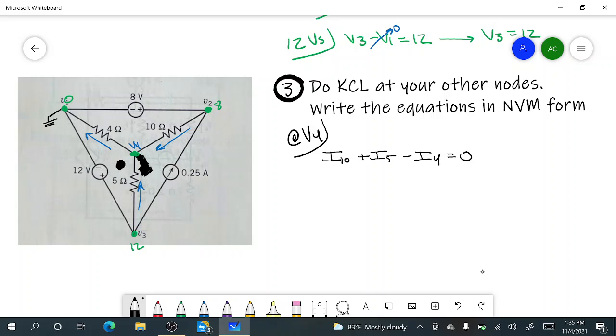All right, no problem. Now, that'd be great if you were just doing KCL, but we're doing node voltage method. Node voltage method is just a fancy way of doing, well, I should say a more complete way of doing KCL, okay? So we're going to convert our KCL equation into the node voltage rendition of it, okay? Remember this, currents always go from the plus term to the minus term. Current goes from plus to minus. So that's going to be the way we kind of think about it. I'm going to erase all of that, of course, because it's just a lot for me to have on one diagram. But if you think of it as the current goes from the plus to the minus, and remember, let's just use the 10 first. It'll start on the plus here, and then it'll end on the minus there.